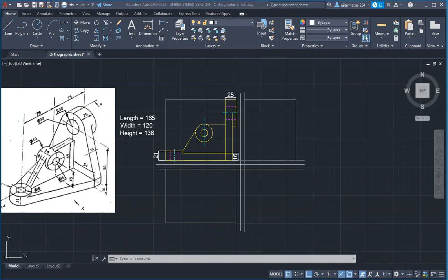Yeah, Isha, go on with your question. Sir, but from front view, we cannot see that center line, right? From front view, we are not able to see it. Now that is why we have made it a hidden line, right? No, also the center line. A center line is something which is not about seen or not seen; we are not talking about that here. A center line represents that there is a circular section or a curved section.